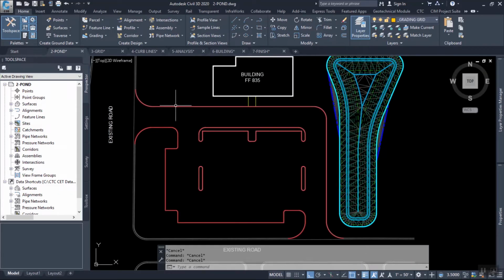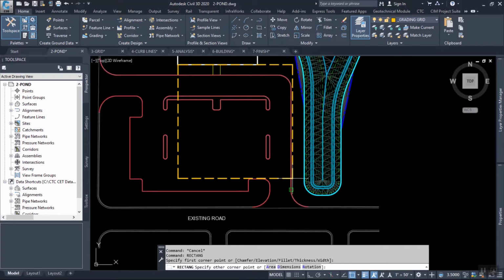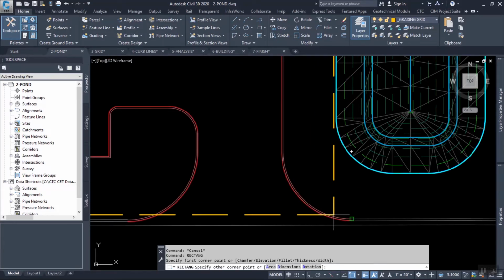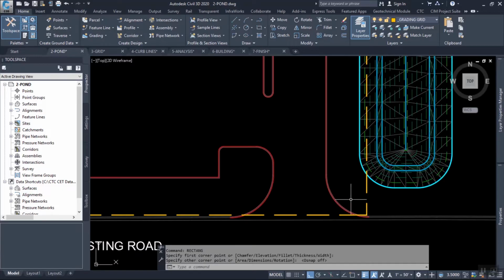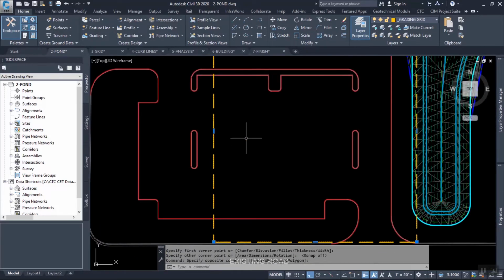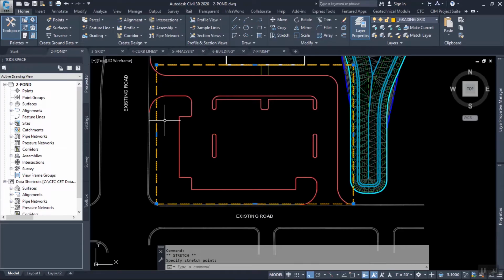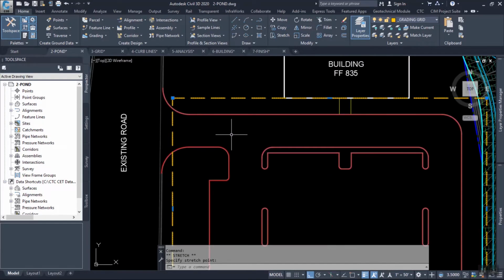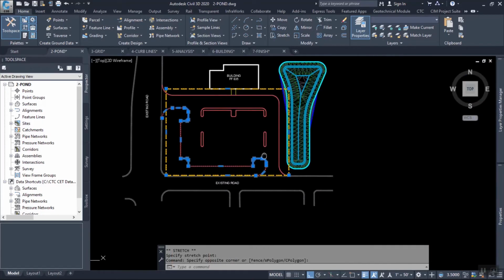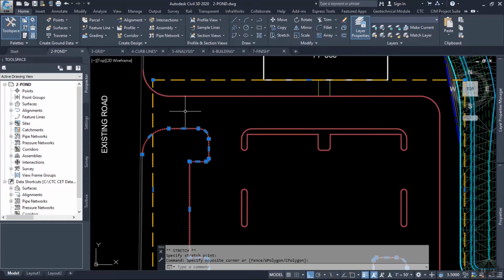So a setup surface is a simple surface that defines a drainage pattern. And if it's a fairly simple site like this, I start with a rectangle. What you want to do is draw a rectangle that covers every vertex in your feature lines except where it has to tie into an existing. Okay? Now ideally we would control all these elevations with this setup surface, but again, like I said, we'll break away from it where we need to.